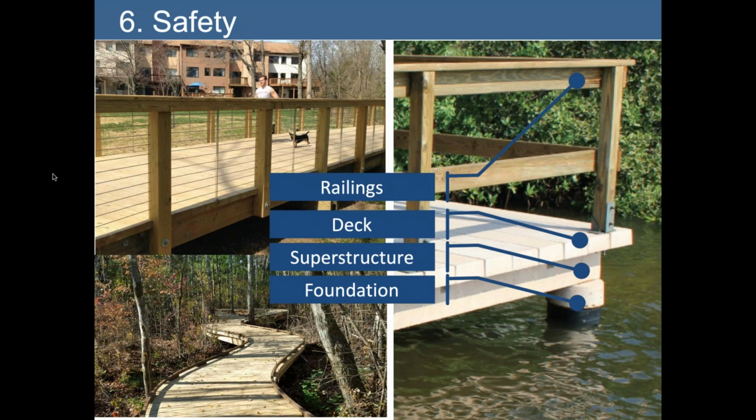Of course, the foundation system has to be designed per code to a safe design, to a design code, but the railings are commonly something where the designer has to make a decision. And from the building codes, you will see that a railing is required when a structure such as a pedestrian bridge or a walkway is elevated 30 inches or more above the ground. On the right-hand side, obviously, there's a railing there because you're over a body of water.